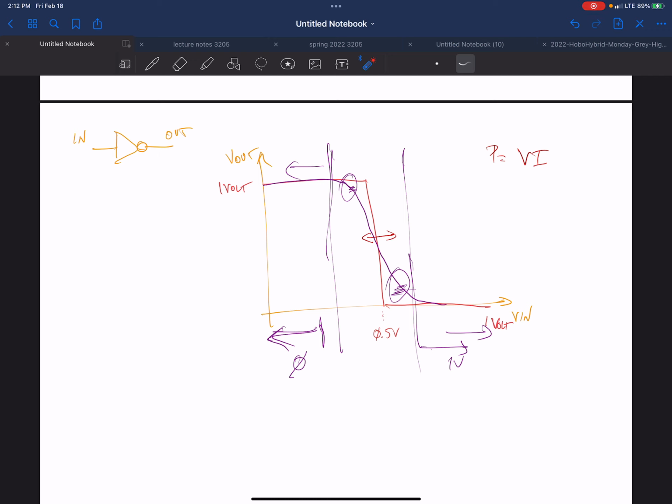So, long story short, reason number 2 for CMOS being good and popular is your noise margin. Your rejection of noise is very good in CMOS because of these factors: you use the full power supply, you can set your threshold value relatively easily, and so you can optimize your noise margin. So that comes into reliability.